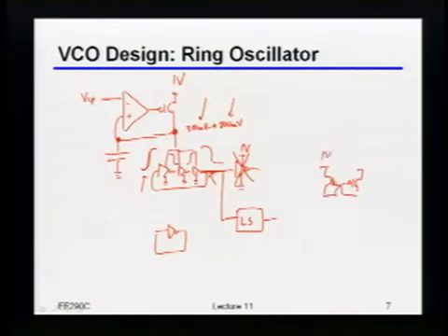So presumably this is 1 volt, that's 1 volt. And then you said two NMOSs at the input. Now, what are those two NMOSs driven by? Complementary versions of the input. Okay, so for example this would be clock, and then I would need another inverter there, which is still running off of the regulated supply, to get the complementary version.